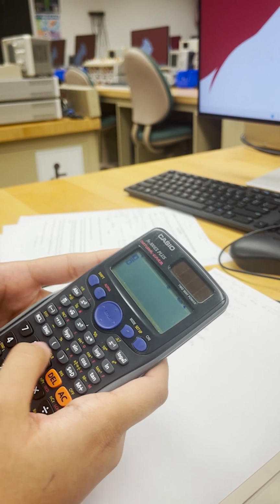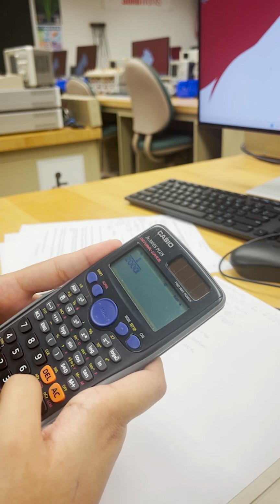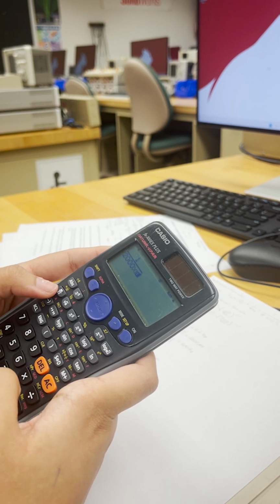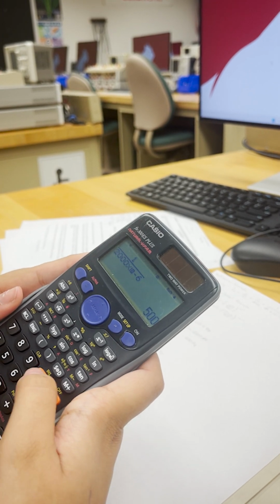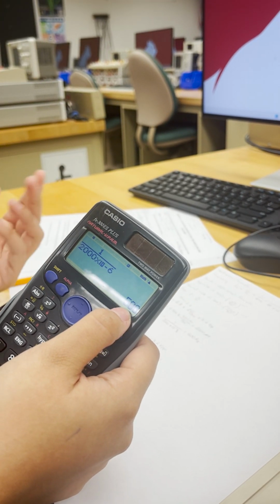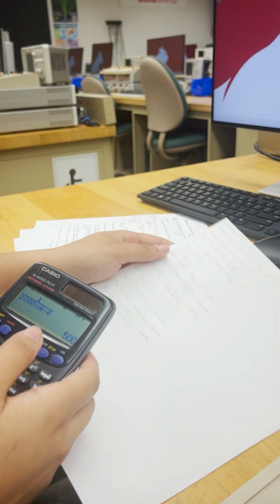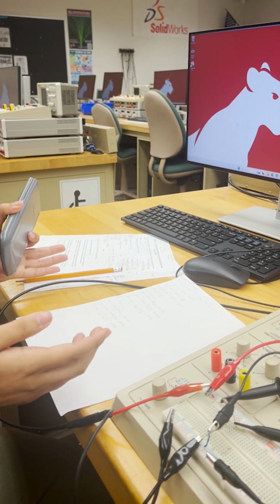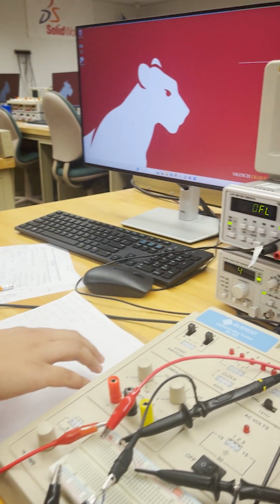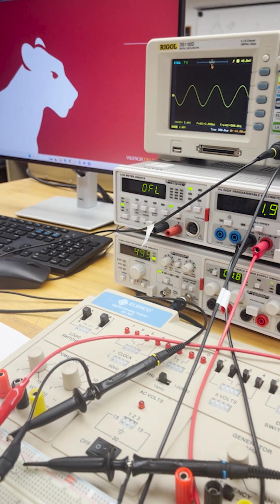In order to get frequencies, just gonna go and do 1 over our 2,000. We're converting it from microseconds to hertz, and our hertz value or our frequency is going to be 500 hertz, which matches both our Multisim and the original frequencies that we had inputted into the system.